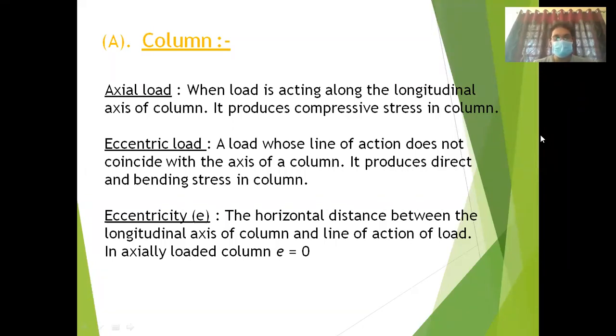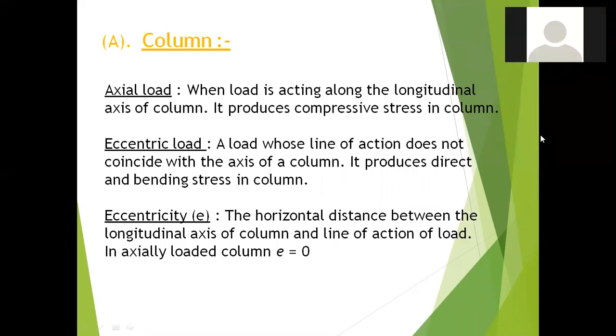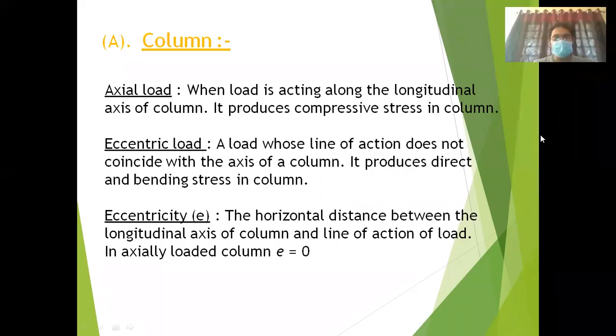Here, eccentric load means the load which is acting on the cross section of the column a bit away from the center of gravity of the section. That makes the member have eccentric bending stresses.